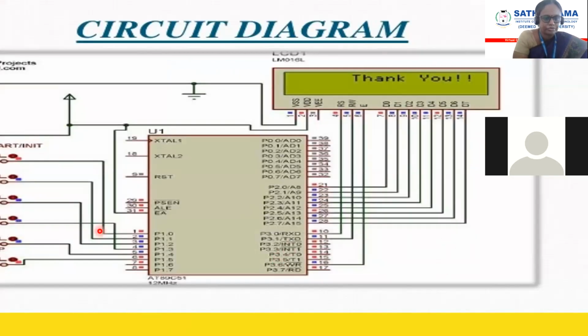This is the circuit diagram of EVM. The input part consists of 6 switches. 4 switches are active low, connected from port 1 first bit to port 1 fourth bit, and the remaining 2 switches are also active low, connected at port 1 0 bit and port 1 fifth bit.